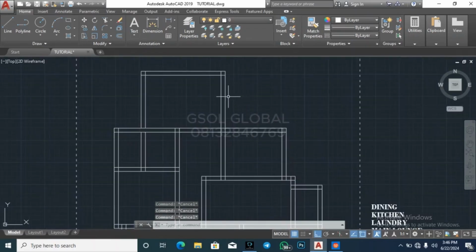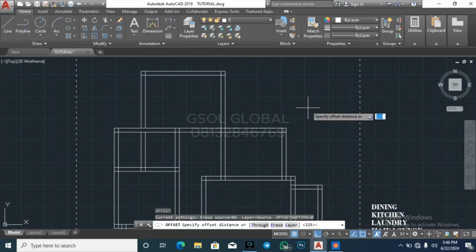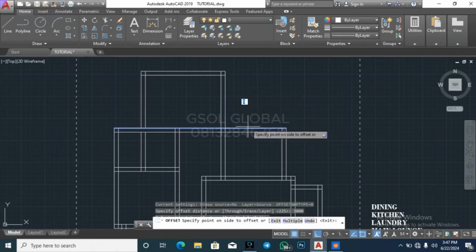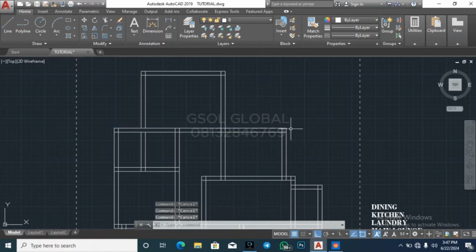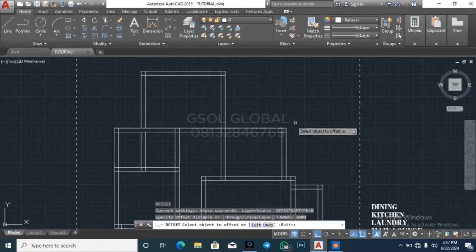So now this space will act as our porch for both the laundry and the kitchen. So let me go ahead and just draw it so both can access the porch. So I'll make an offset of, let's say, 3 meters too. So let's see whether we get us to, okay, almost intact. Okay, let's make an offset of 2 meters because it's still having more width.